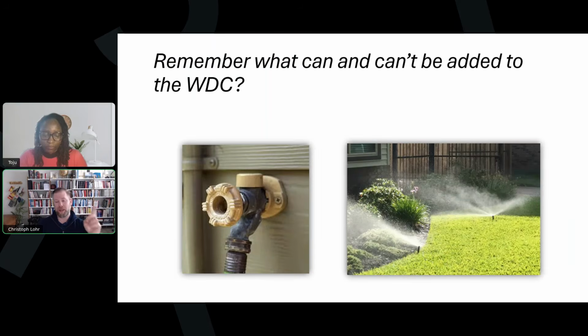That said, some engineers do look at what time the irrigation system is going on. There are discussions and arguments that the irrigation system is not going to run at the peak load, which is likely in the morning hours when the highest peak load is likely to occur. So some engineers treat that as a separate load and don't add it. There are certainly ongoing discussions in Z1403 and other areas around this, so expect to see a little more definition in the near future.